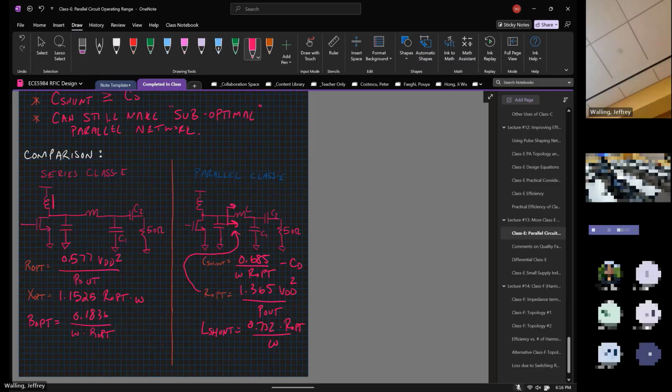Well, the total impedance of that node is really just the shunt combination of all of those parallel items. So it wouldn't be a problem, but do remember that at least some portion of that capacitance is innately going to go to ground because it's coming in parallel with the transistor.